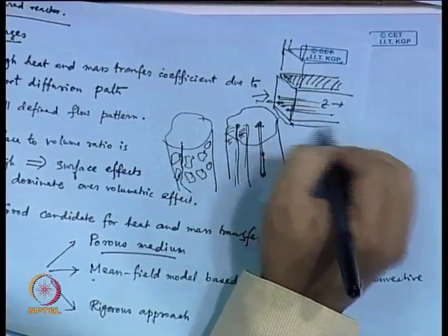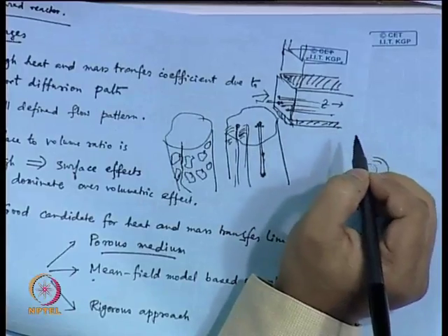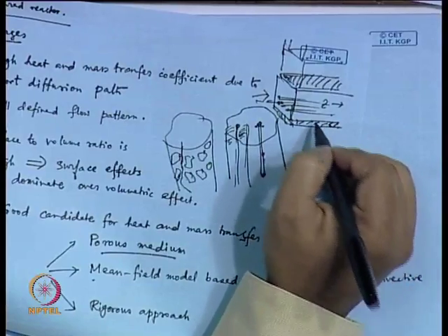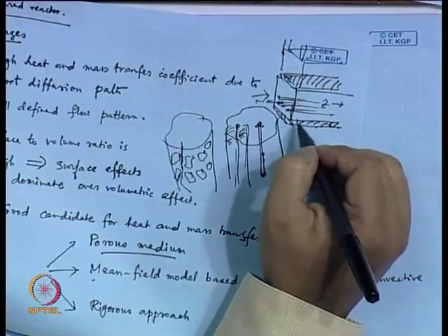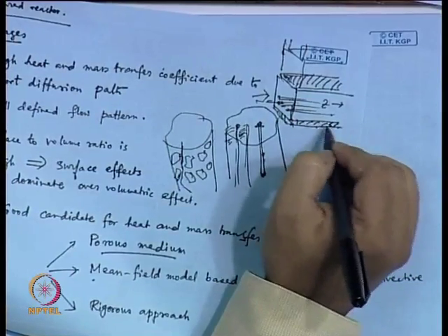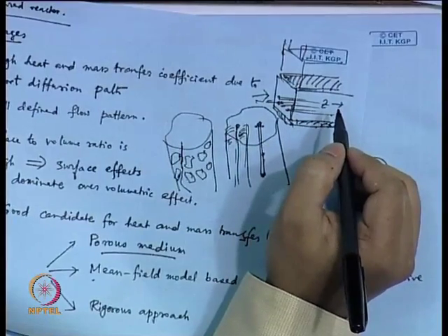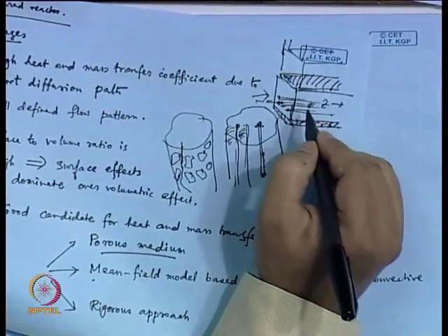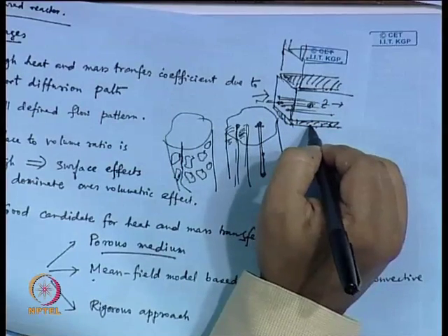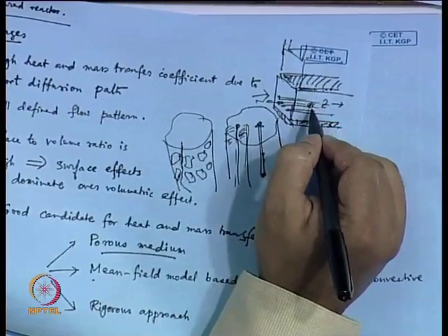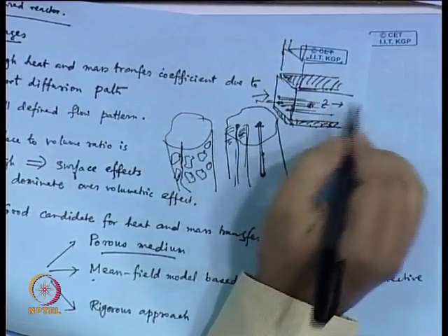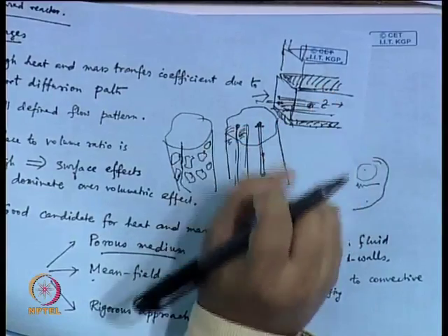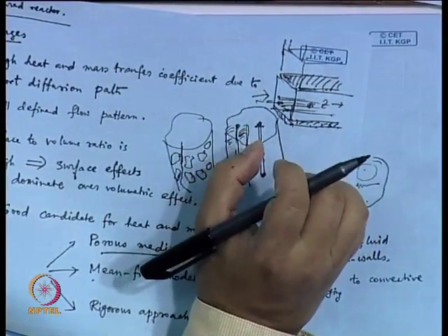Suppose here there is another heating layer. Suppose you are talking about an endothermic reaction, that means the feed is taking the heat. So you have a heating layer, a hot fluid flowing through this, or by some other means you are heating this layer, all right. So you have this heating layer here and here, then which place would be the coldest within this block? It should be the center, right, by symmetry. So this area would be the coldest, and here it would be the most heated. So you can expect within this block there is a temperature profile. Now, this block has thousands or millions of channels, that is another issue, and the feed is flowing through these channels and taking the heat. When the gas is flowing through this channel, it is absorbing the heat, right.